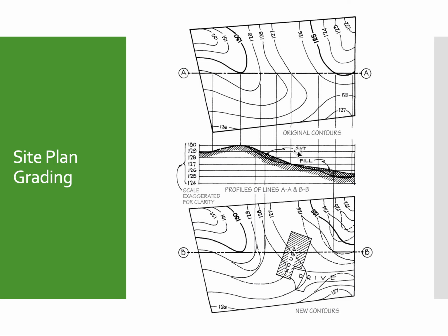And you can see something called cut and fill. And that is showing you an example down here. The house was decided to be located here, so we had to modify the terrain to avoid water running into the house, because you create all kinds of problems when your house floods. And so if you bring these lines, cut through here, this is a cut line, you cut through here and you bring these lines down, they will correspond to where the terrain is on the map.